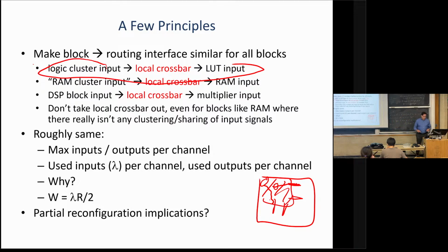So the first versions of partial reconfig, which were done by Xilinx, did go straight to wires, okay? And they were harder to route. And in Stratix 5, Altera chips never supported partial reconfig, partly for patent reasons. Actually, there was a patent that we couldn't design around for a long time, but eventually when the patents were cross-licensed, the lawsuits were settled. We could just use this idea. We got clever. We basically went, well, we're not going to do that.